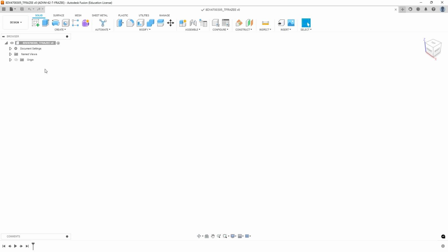Okay. Yeah, the advantage of saving this up front is it starts the auto recovery. If you do a bunch of modeling and then save the part, your auto recovery won't start at the beginning, and you'll lose work if you crash.